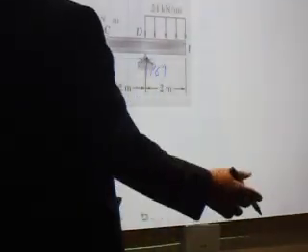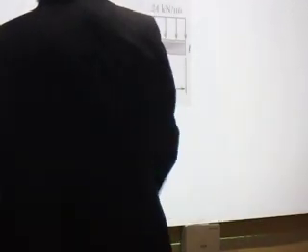Now, we can start by drawing the bending moment and shear force diagram. So I'll draw the shear force above it and the bending moment beneath it because of the area here. Okay? So shear force diagram, I'll go up like that. The easiest thing is to go place the points like this. Okay? So if I'm drawing here the shear force diagram, 28 down, this is negative 28. Then it's constant. It receives the 76.